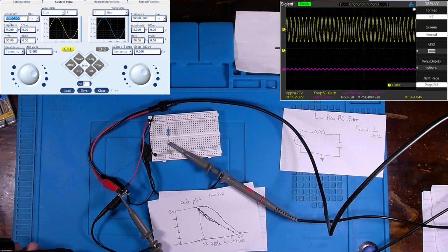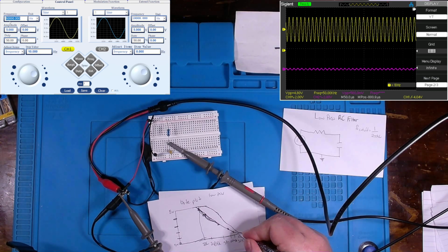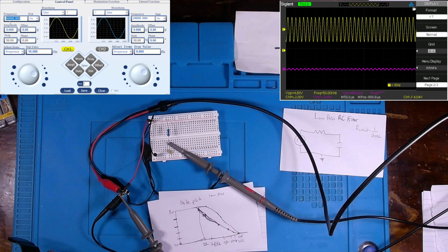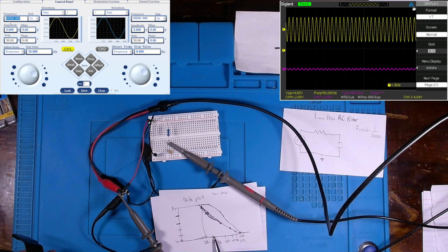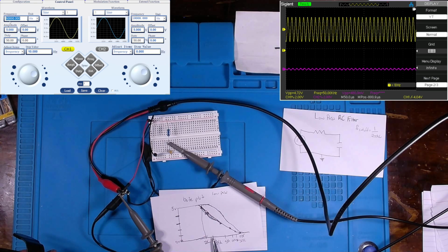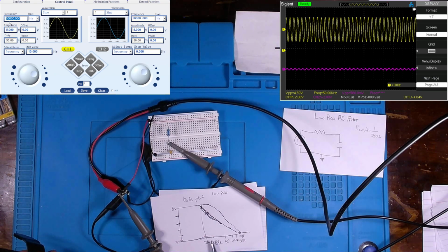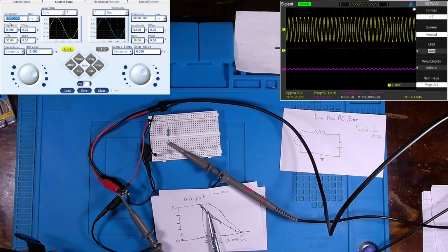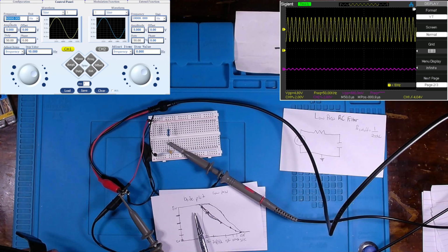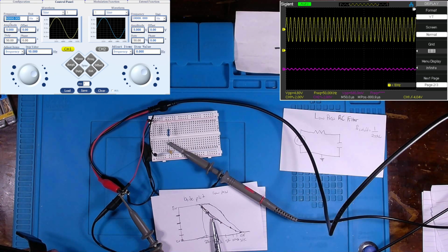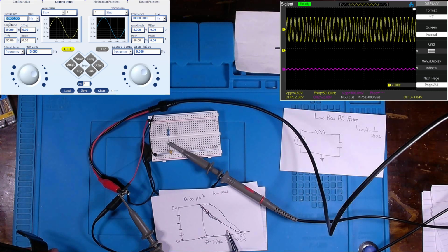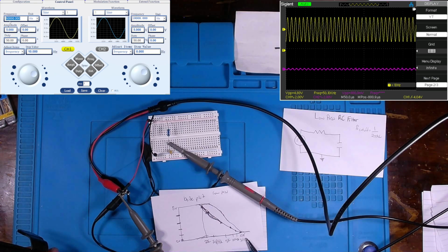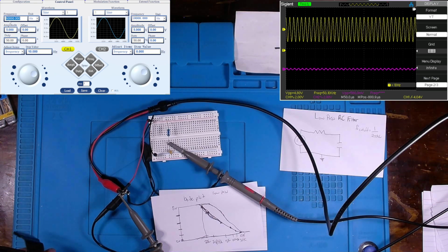And you know, 500 millivolts, so half a volt. We're practically getting close to the floor. But you can see how it starts to attenuate before we actually get to 2,842 hertz. It starts to attenuate at 2,000 hertz, and then it continues, and the higher the frequency gets, the more rapidly that attenuation increases, all the way up to, say, 50K there.